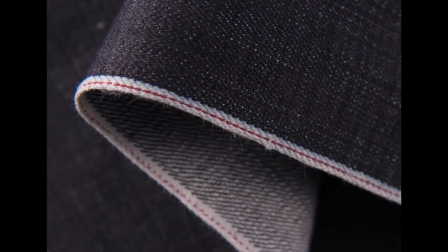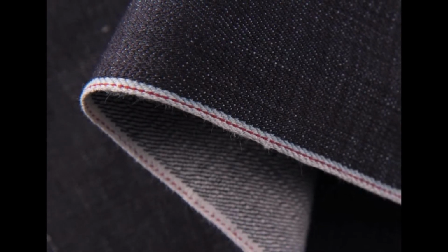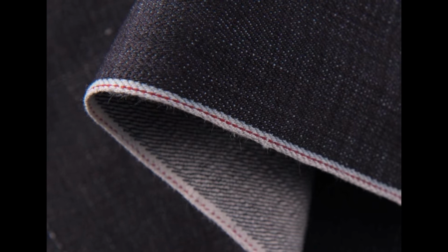But this edge sometimes, in order to make it stronger, has more yarns placed over there, warp yarns, so that this becomes a little thicker when compared to the rest of the fabric, and it will also be very strong, so that even if you want to tear it, it is not possible to tear the fabric as such. For fabrics that are made into garments, usually 1.25 centimeters or 1 centimeter selvage will be present. Maybe for bed sheets and such, you may find a tape selvage, which is a little wider than the ones used for apparels.